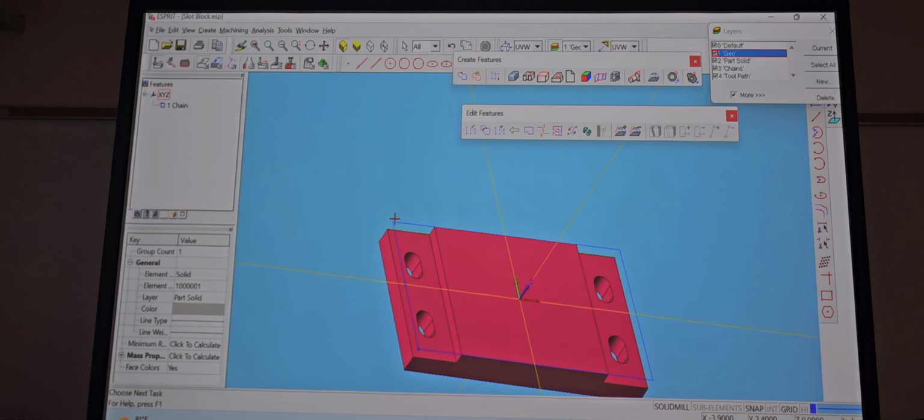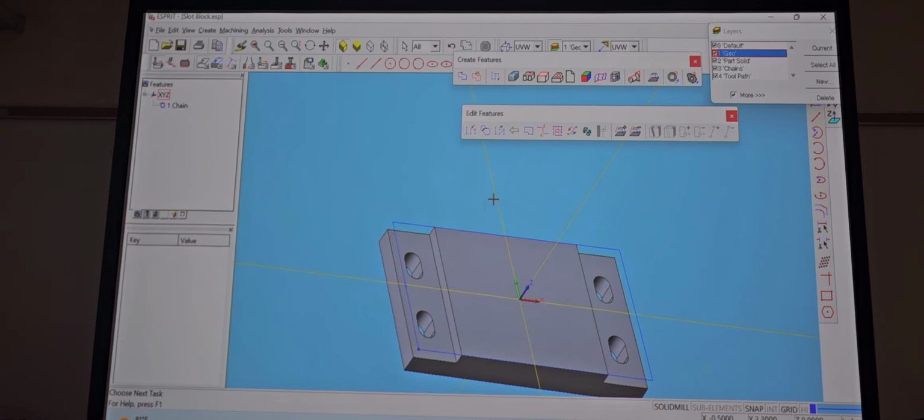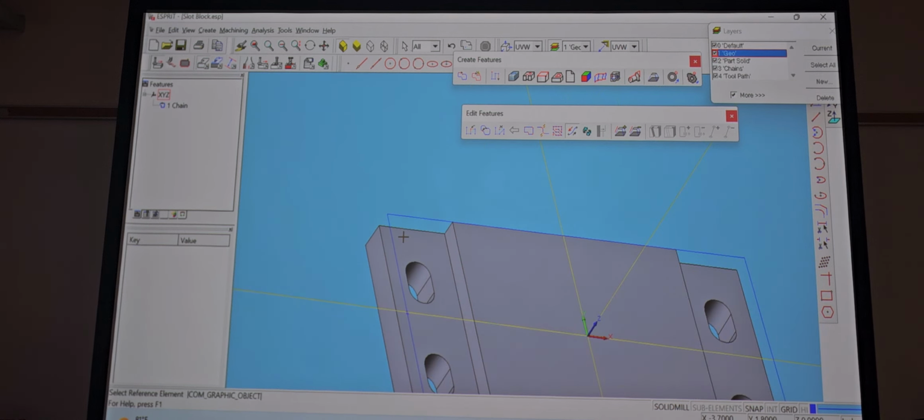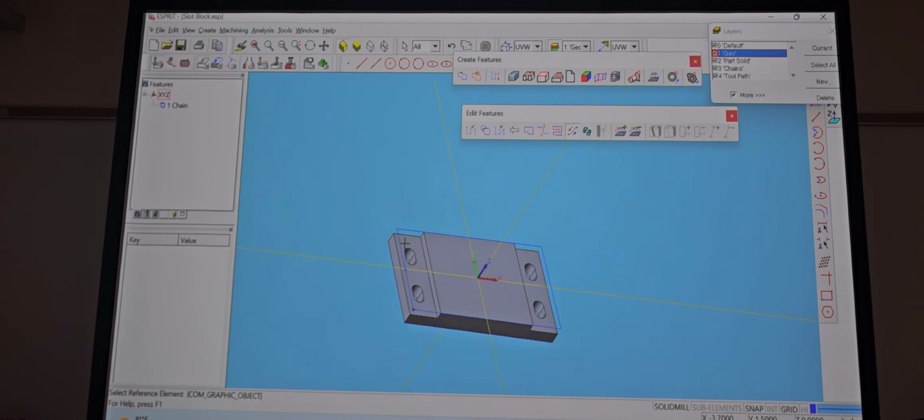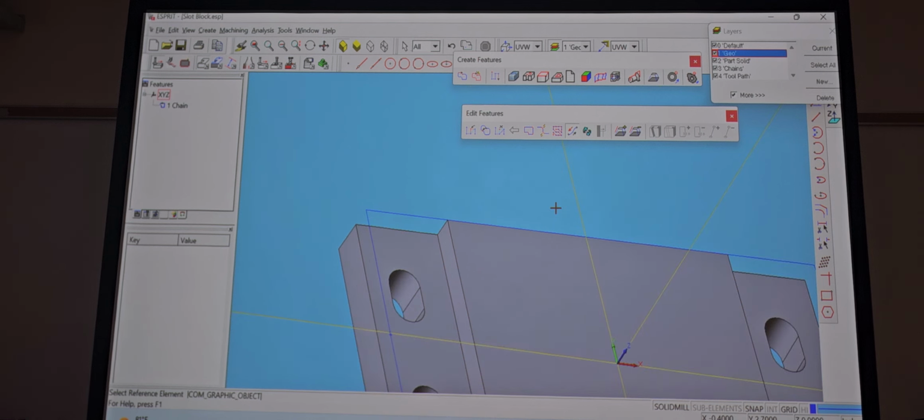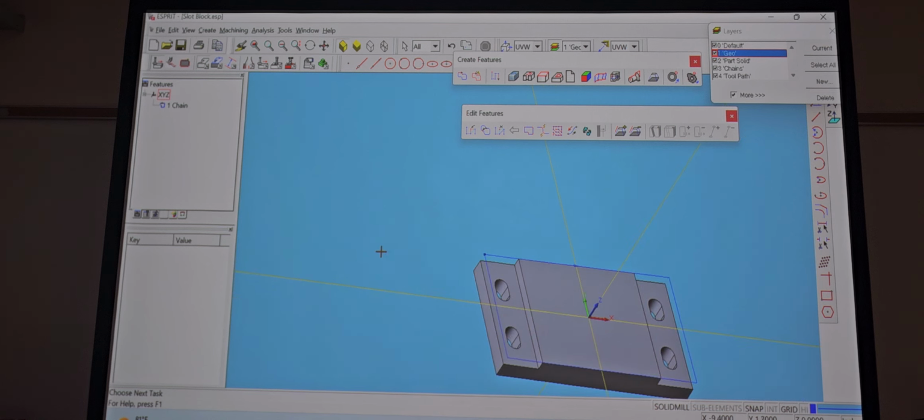And it always chooses, because I was trying to do that with the gear, start it in the middle of the part, but it wouldn't. It always chose a corner, right, because it needs to approach it. And the transition is, descend it, yeah. But that's how you would work it out. Play with it a little bit, boom, there it is, right? So I wanted to start here, mill this way, and then come over here. And you could do it bi-directionally, you know, one way, one direction, however you want once you start creating your actual feature. Does that make sense?